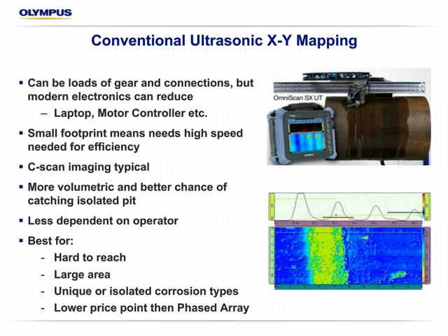So the chances of being able to detect amounts of corrosion, as long as your scan speed is adequate, not too fast, and we keep coupling to the system, it is a very efficient way to do a high resolution scan. And then because we're programming and taking the data automatically, we are really less dependent on the operator.